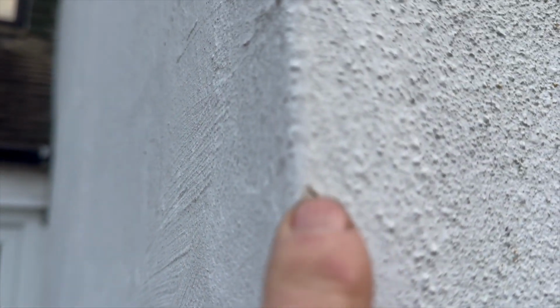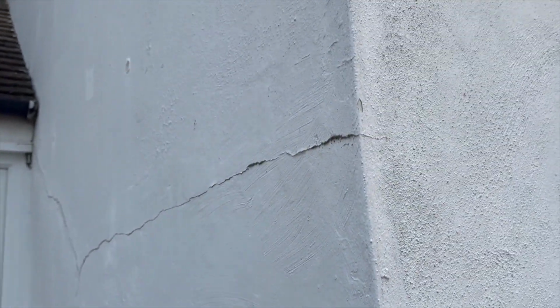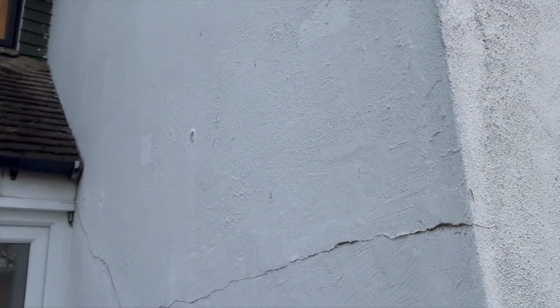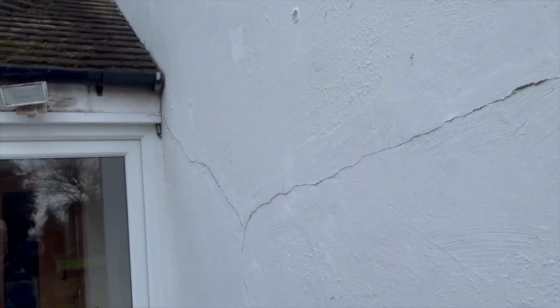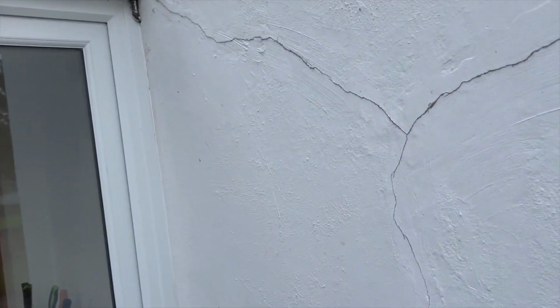There's obviously paint on there. But as a general rule, if you've got impermeable render, you need impermeable paint. Otherwise you can just hide a crack and the water still be absorbed inside. It can cause increased dampness on the inside and therefore increase mould.